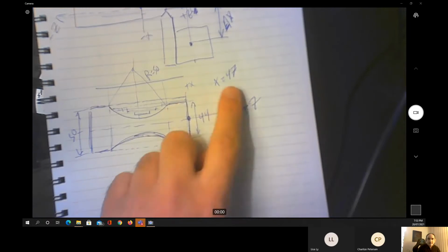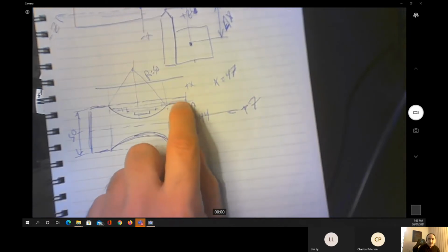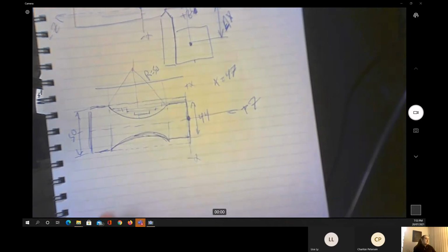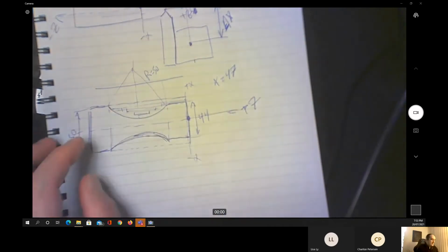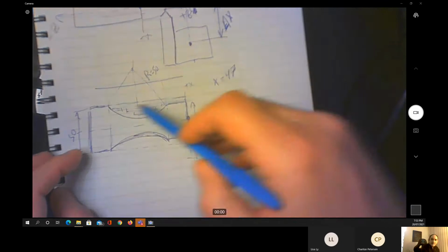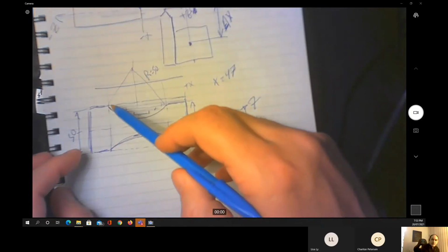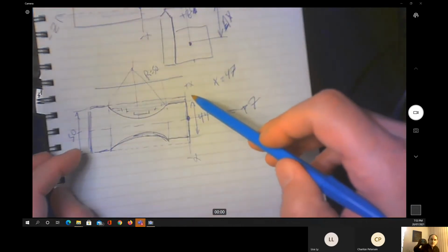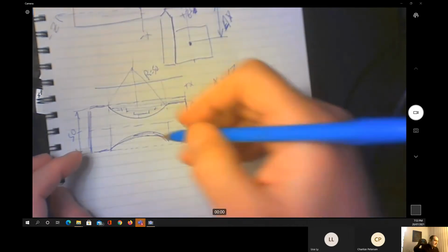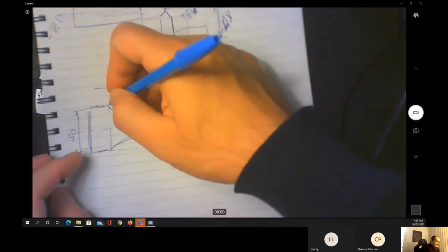So it's going to be X equal to 44 at this level. I'm defining the diameter I would like to cut, not the radius. So I'm going to start with the first 2 lines to remove layers until we get the diameter from 50 to 44.